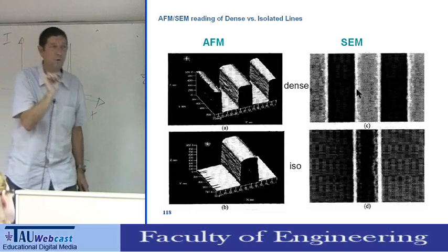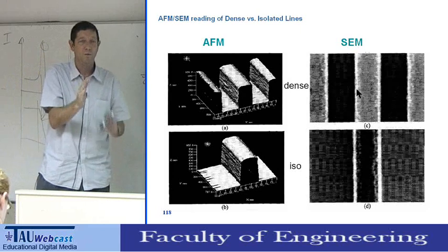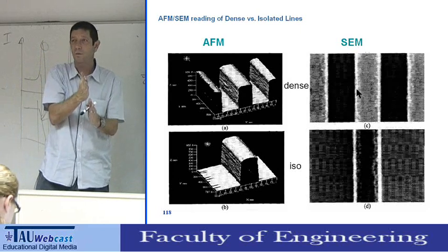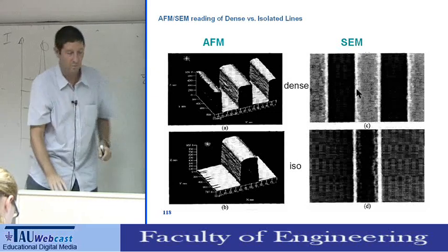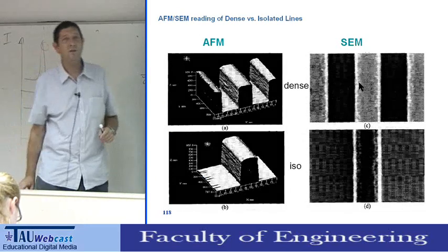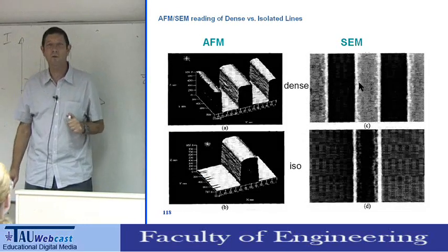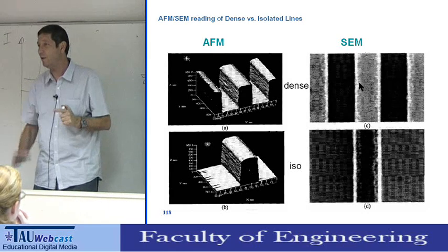So the conclusion from these images is that even SEM, which is a very accurate method, has some uncertainty because of the slope of the lines, so we need to calibrate it. Is it an error or actually the slope of the line? It's a good question. The question is whether it is an error or just what I would call a bias, like a constant fixed error.